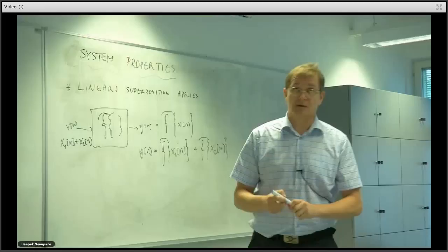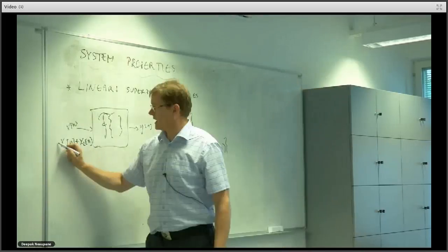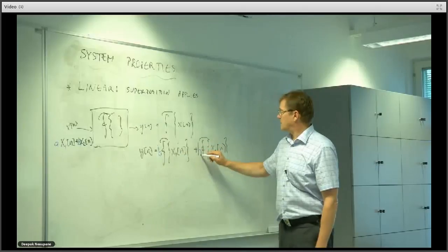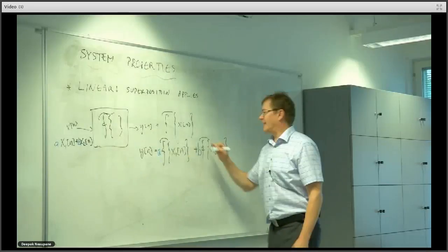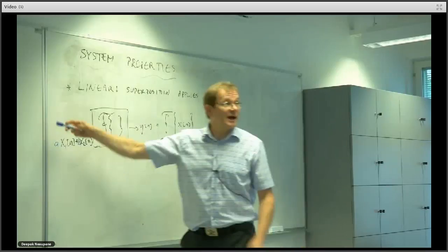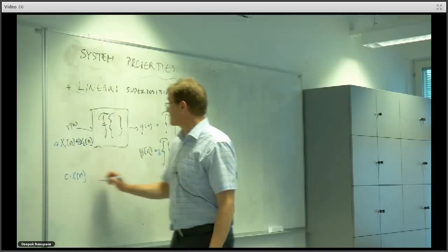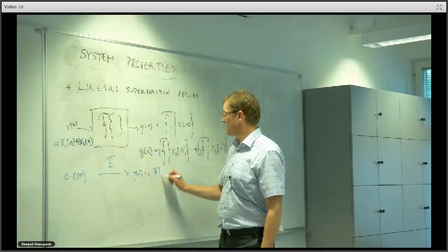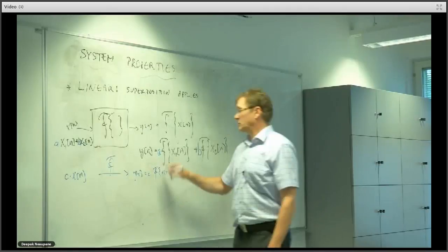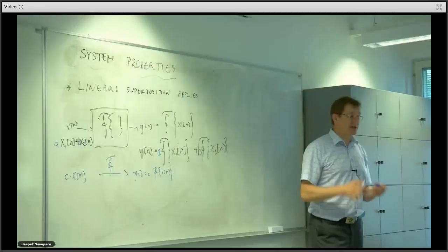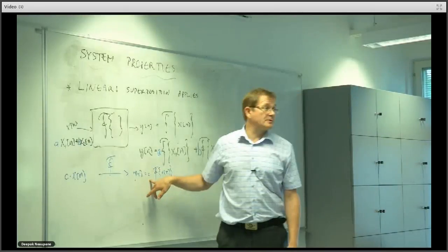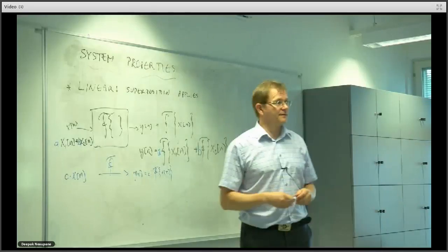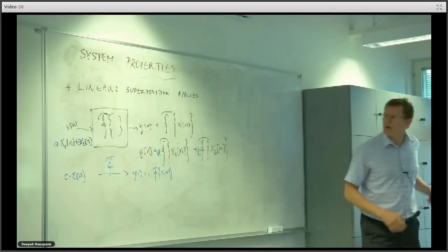Same actually, it's also on linear systems. You can have scaling factors, say A and B here. If the system is linear, then the scaling can be taken out of this equation. So basically, if you multiply a signal, say c times x of n goes in, then after the system, y of n should also be c times whatever the system output was before the scaling. Okay, simple but very important factor. So this actually states that you can turn up the amplification of the signal either here or on the other side. And again, well, this microphone kind of thing is never totally linear in a mathematical sense. Okay.